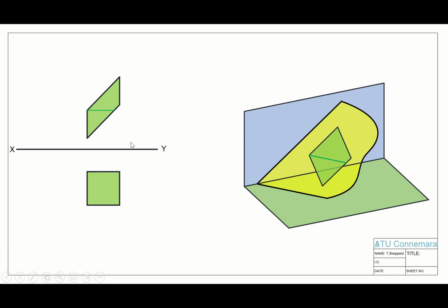So we can see we have our point here already in our plan view. We just project this down onto our front edge here, giving us the angle of our trace line, or what's known as our strike line in our plan view. And because that line is a horizontal line in elevation, it will be a true length line in plan view.